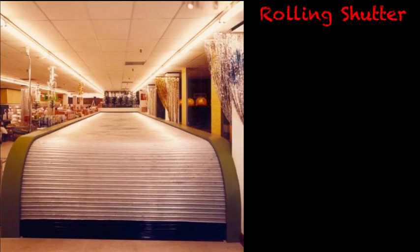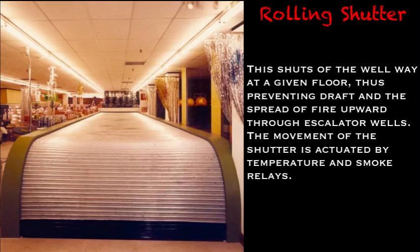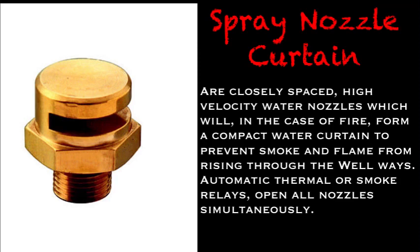Rolling shutter. This shuts off the wellway at a given floor, thus preventing draft and the spread of fire upward through escalator wells. The movement of the shutter is activated by temperature and smoke relays. Spray nozzle curtain. Closely spaced high-velocity water nozzles will, in case of fire, form a compact water curtain to prevent smoke and flame from rising through the wellways. Automatic thermal or smoke relays open all nozzles simultaneously.